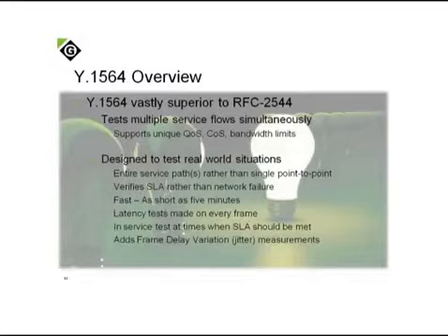And it also adds frame delay variation, or jitter, measurements. Now, our RFC 2544 folks may be saying, hey, I can test jitter in RFC 2544. And test equipment manufacturers have added that over the years at the request of customers. Not part of the original standard, though. Jitter was never taken into account when testing RFC 2544. So that's an evolution, even showing that 2544 had to be adapted to meet what we needed.